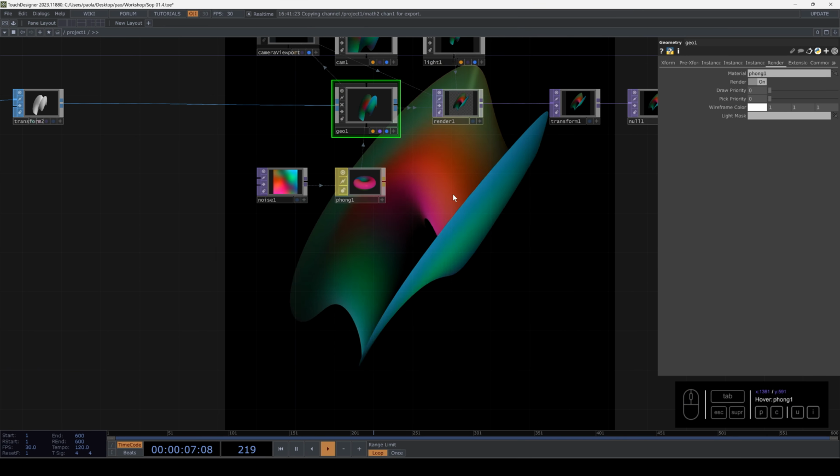We can put more lights, yes. Right now the light is in front of the object, I can show you. So for example, what I like to do is have this light in the front. I'm going to copy and paste. Light in the left, -10, 0. So I have a light there. I like to put another to the right. That will be 10 positive here. And we have much better full color everywhere.